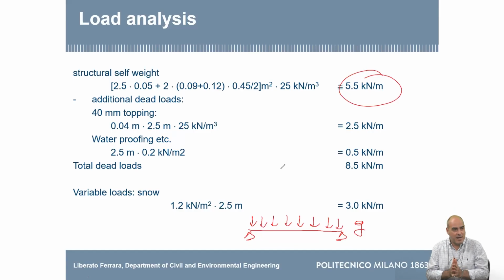But generally, in northern Italy, the snow loads are worse than the maintenance loads. But there may be cases, for example, in southern Italy, where the snow loads are lower, at 0.6 kilonewton per square meter, and the maintenance load in some cases can be worse, depending on what kind of roof. This is also just to show you that we have not done any structural design calculation so far, but if you don't lay out these assumptions, you will make calculations which are not representative. So before going into a software, into a calculation and so on, have very clear what your problem is.